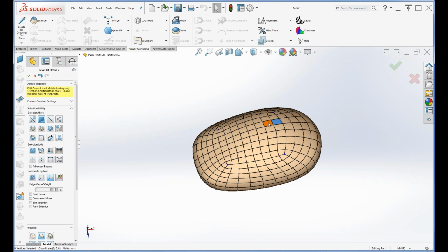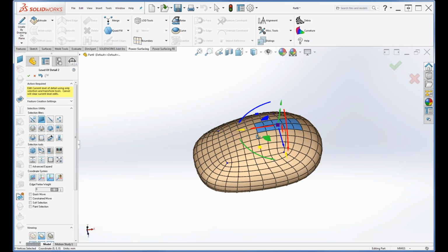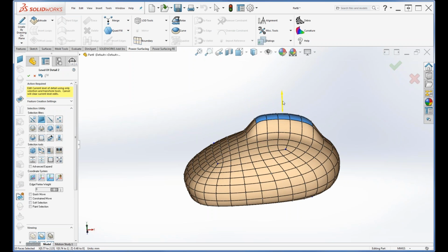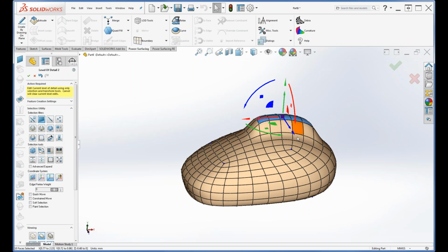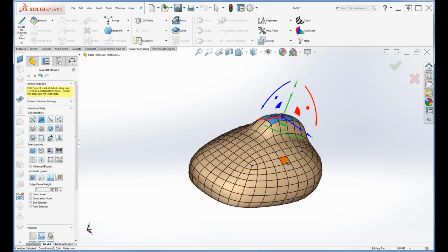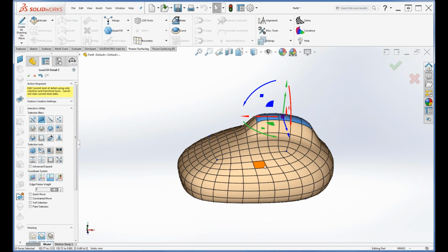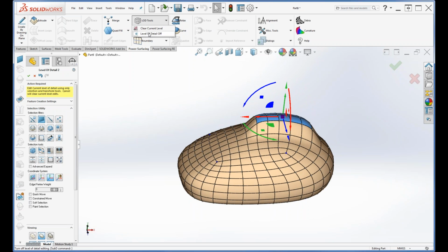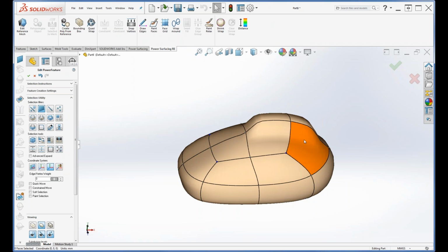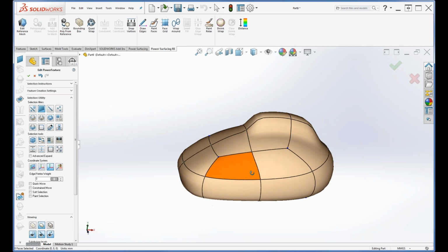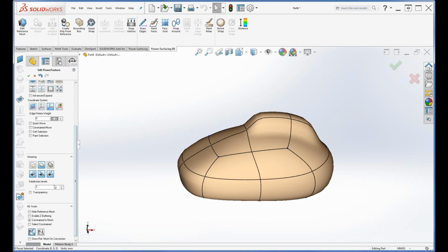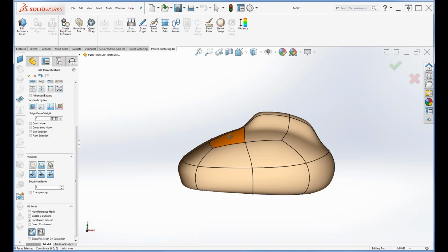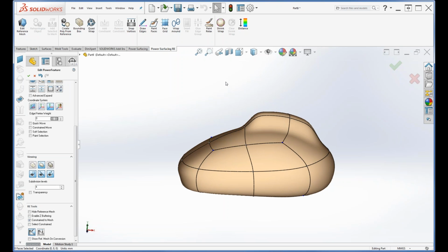And I can go in and I can select some stuff. I can't do an extrude. The only thing you can do in level of detail is transform, move, rotate, or scale. But it's going to add that transform to the transform that left it on the actual reference mesh. And if I exit my level of detail, you can see it retains that because that's on a lower level. It's a little bit chunky looking, so sometimes if you're working at higher levels, you might want to bump up your subdivision level 1.